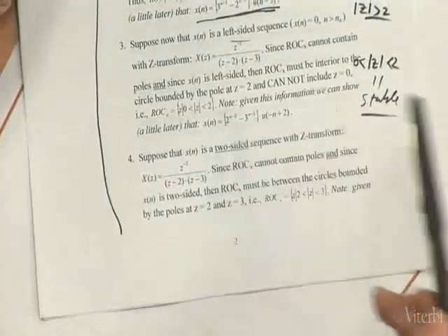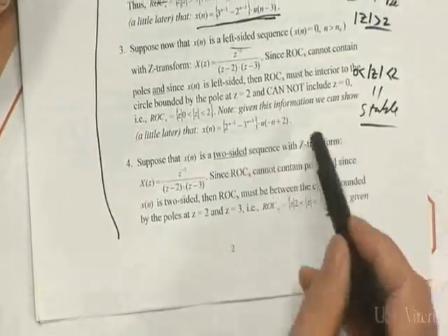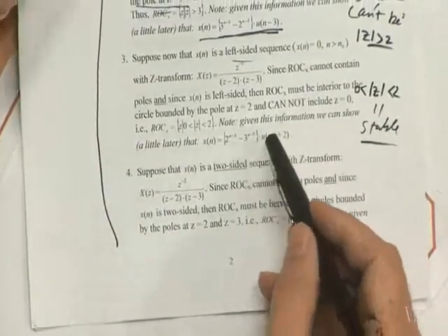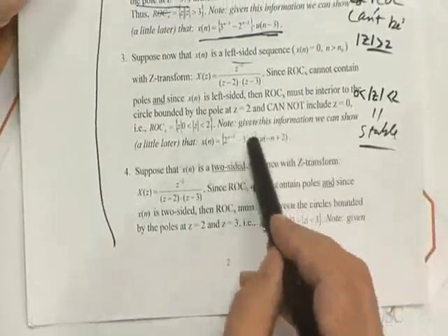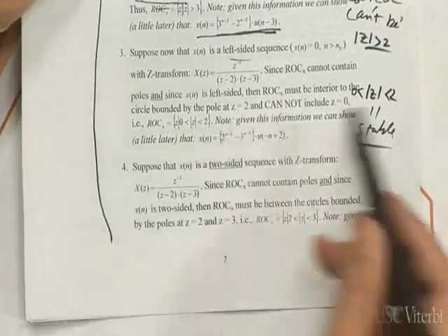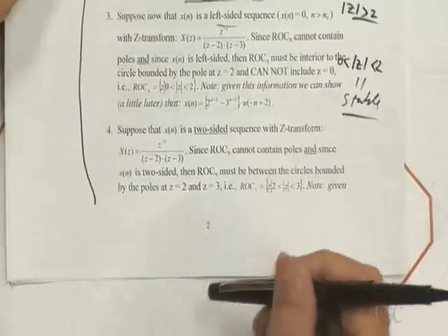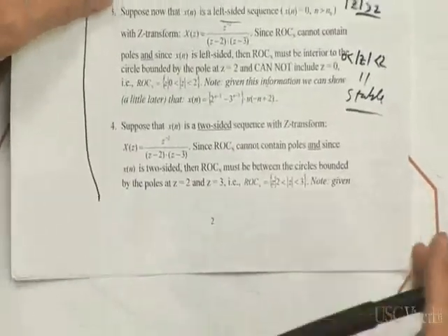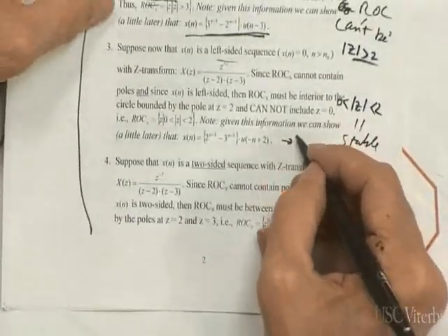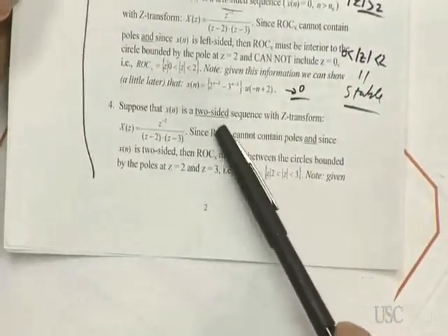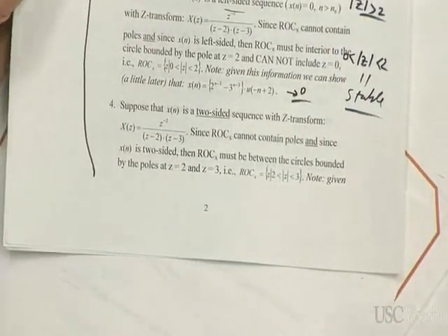And in fact, this is the result for the inverse Z transform. It looks like this. It looks like kind of the same form, except instead of u of n, it's u of minus n plus 2, which means that n is negative. So what seem to be positive powers of n really are negative powers of positive values. So sure enough, that goes to 0, as you would expect.